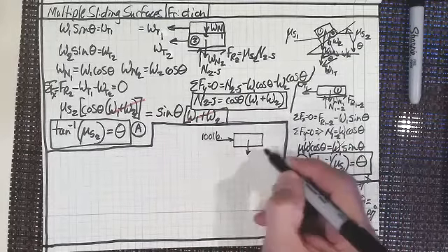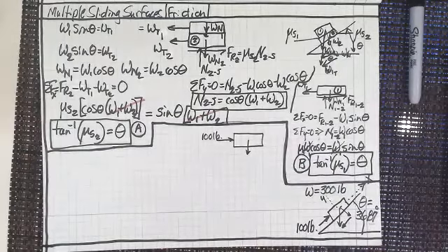And then I'm going to have a force down here. Why don't we figure out what that force is, right? We know that that force is going to be the cosine of 36.87, right? So 300 pounds times the cosine of 36.87 gives me 240 pounds.